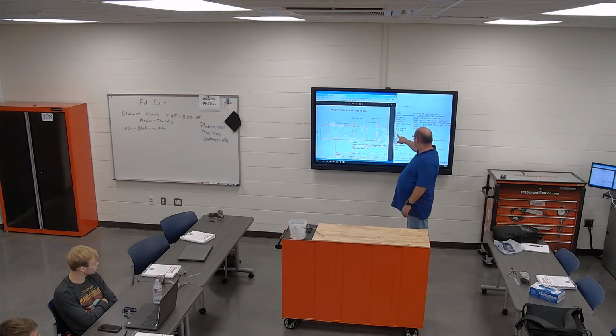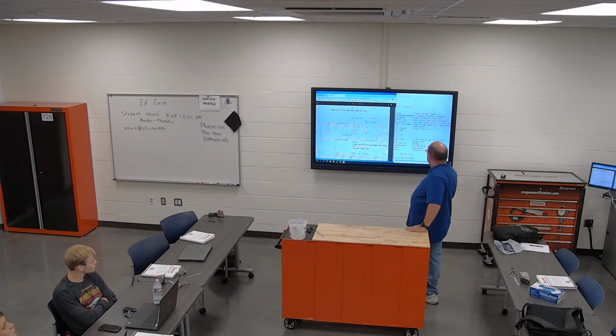So it drops 100, and then it drops down to 125, and then it goes back the other way. Finish it off. So the first pass takes almost nothing, the second pass takes 100, and the last pass takes more of a finish, 25 more. So you'll get a better surface finish.